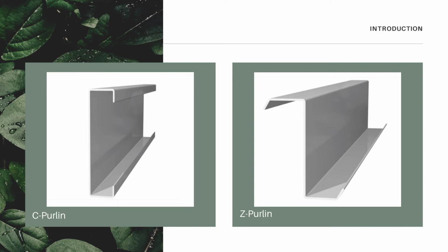straightness and durability. Z-purlins are horizontal beams that form the roof and wall joists of a building shell structure. The shape of the purlins helps in overlapping the joint, which makes it stronger and sturdier than C-purlins. They are often used on large-scale structures because of their strength. The advantages of Z-purlins include superior strength. Purlins can also be overlapped and save material by reducing purlin height.